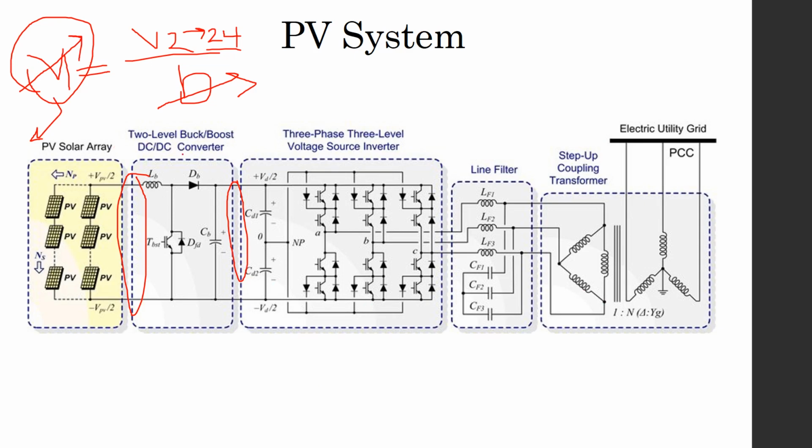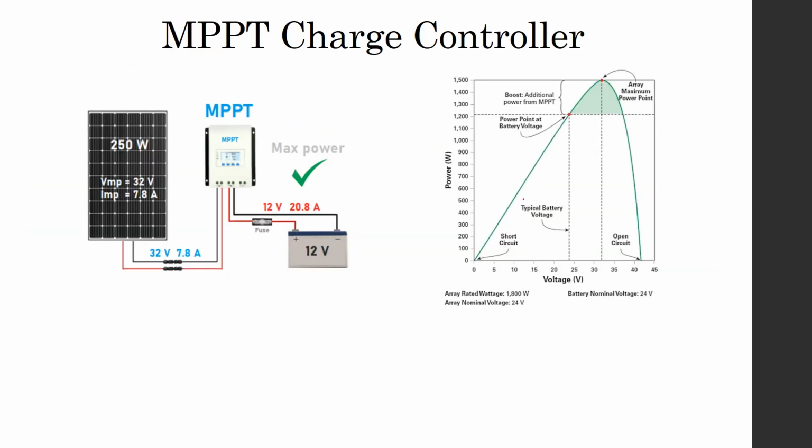So as you see here, neglect the rest of the system now. We are now concentrating this video on the output of the PV array, or on the maximum power point tracking. So if we look at this figure, you can see the relation between the voltage and the power, which we discussed before, at a certain irradiation. So we'll see that at a different output voltage, this voltage is the voltage of the PV array.